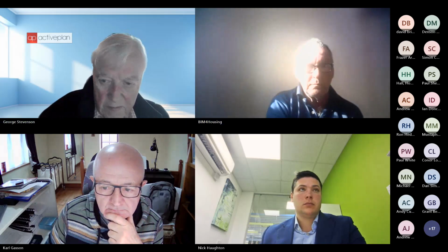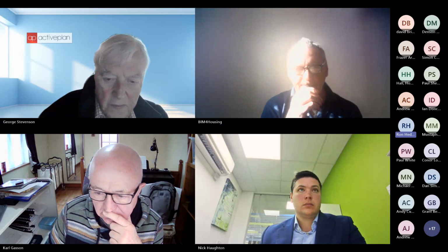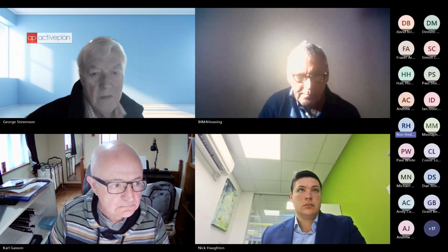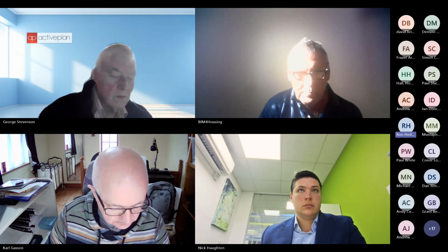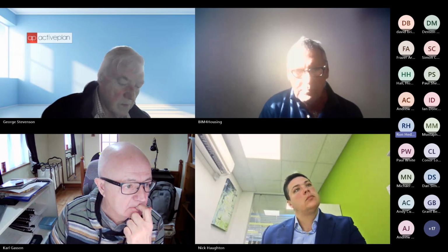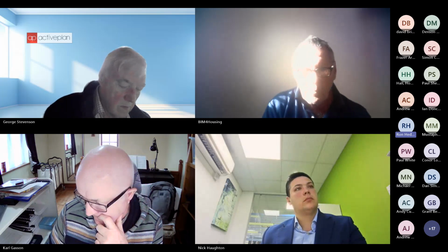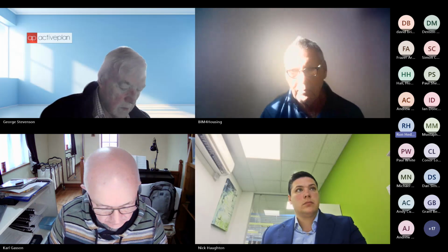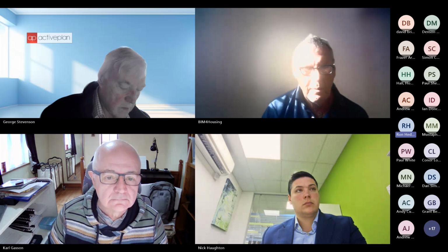Ron. Yeah, I've been struggling with exactly that question for quite a while now. The guidance for the fire risk assessment was until very recently PAS 79 parts 1 and 2, for either housing or commercial. The housing one has now been replaced by British Standard 7972.